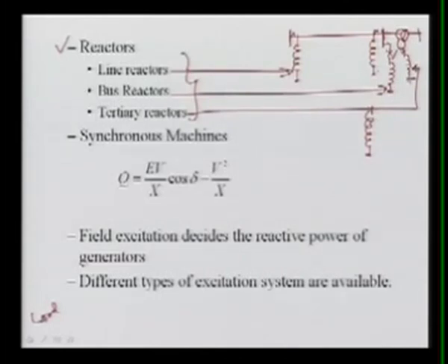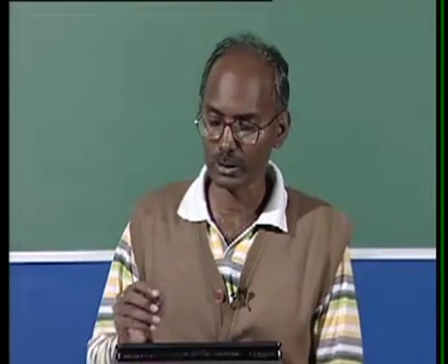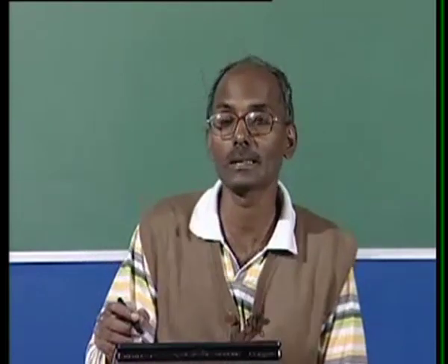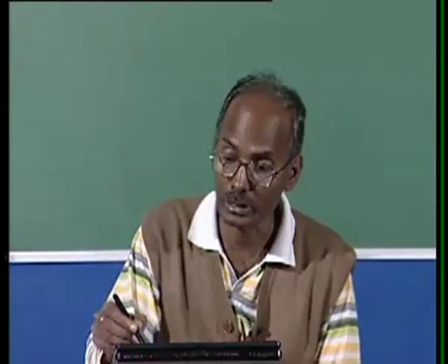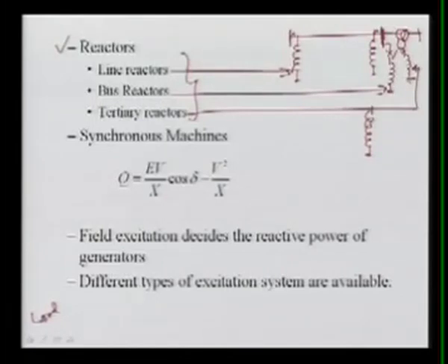Why are we going for the tertiary reactors? The main concern is that these reactors are rated at the line voltage here. This is the voltage of the bus. So here the insulation level and the cost are very high.